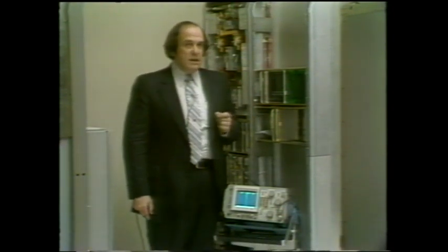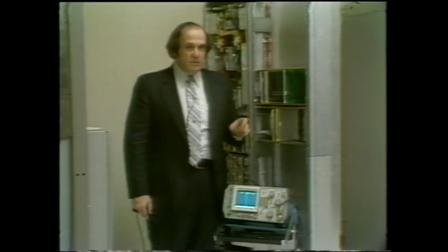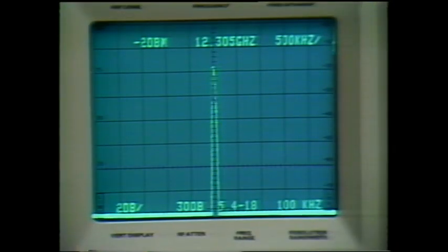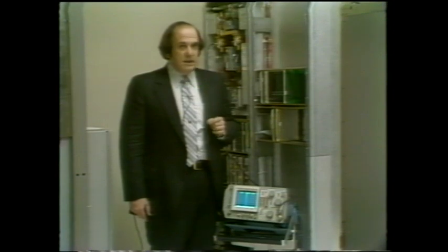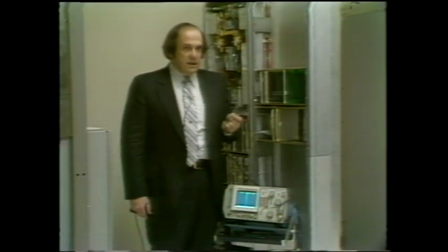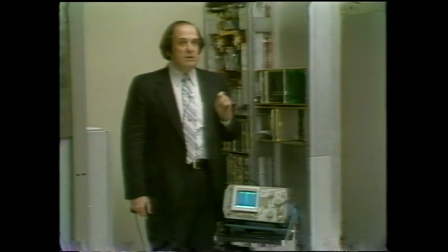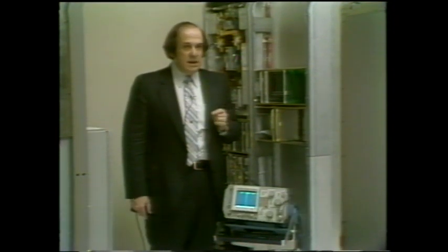Now, this radio is a 12 gigahertz radio in the industrial band, and we'll be making our occupied bandwidth measurement at 50 dB down. But 50 dB down from what? Well, it's 50 dB down from peak carrier. You can see this on the screen because we have turned off the modulation. Now, frequently you're not able to do that. Perhaps you'd have a standby transmitter, but there's always a way to determine where the peak amplitude of our display is, and that's done mathematically.